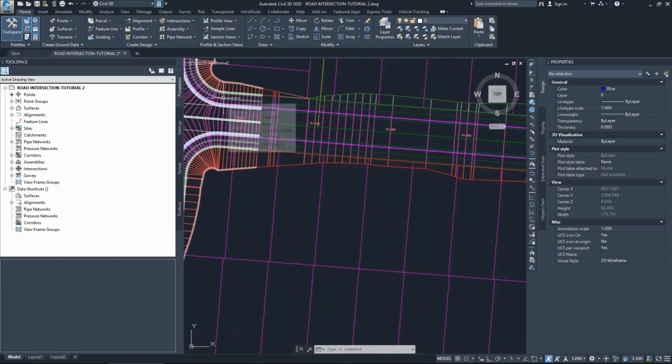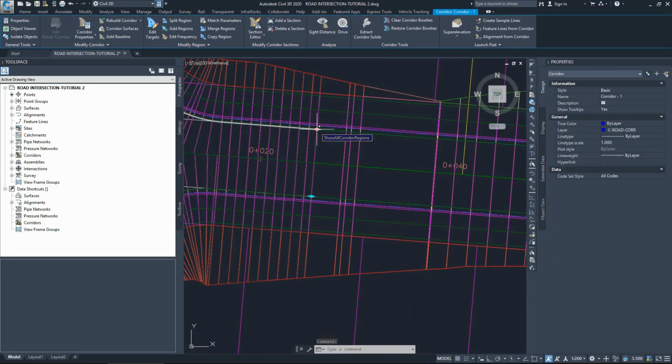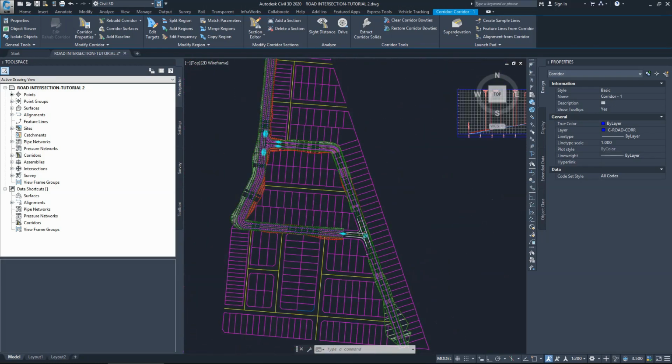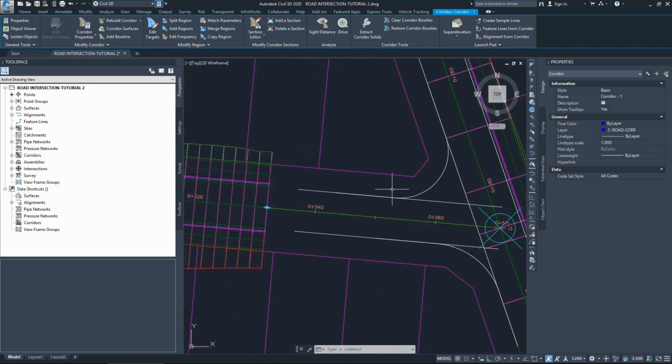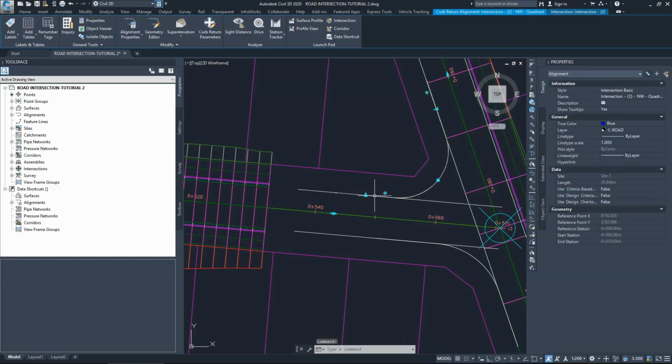which is the end of these corridors, where we get to a point that we need to connect all the corridors together and slide these grid points around so we can get the two corridors to connect together. If you look at those, as we always agree, a corridor has a baseline, and the baseline for these corridors we're creating is this line here as an alignment. So from this point you can tell where the grid point is to draw the corridor of this alignment. In other words, this grid here is the grid we will see at the end of the design that we will start sliding around for the corridor.